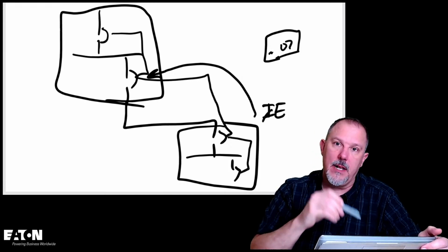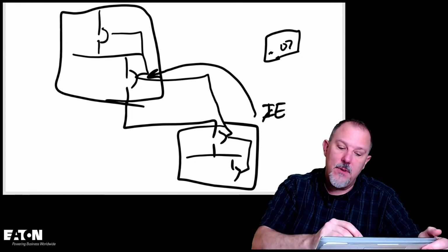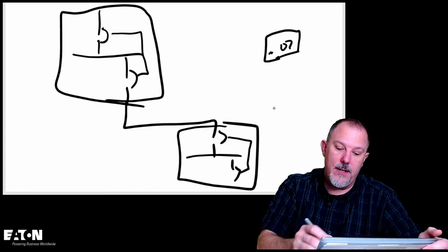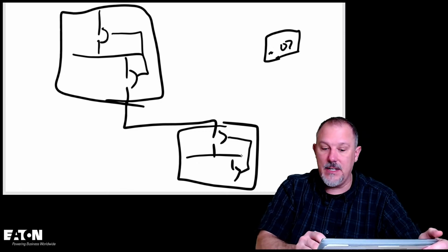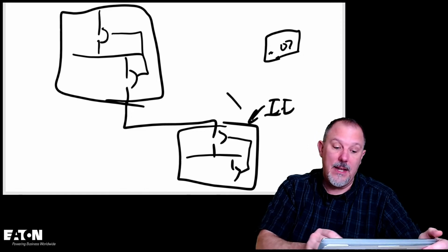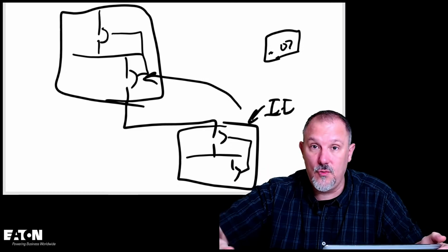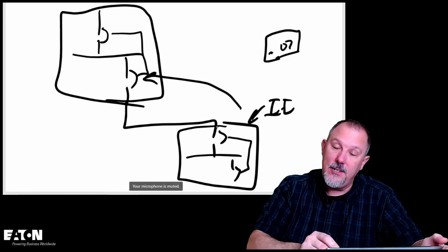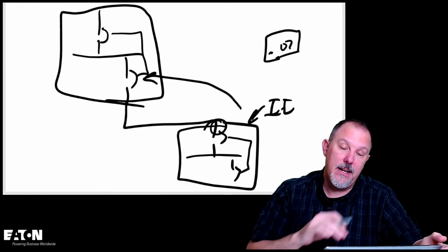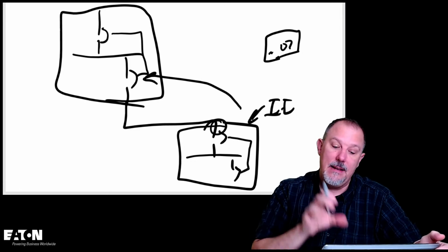So I can nest these, but if I'm not nesting it, if I zone selectively interlock these devices, the incident energy at this panel really is dependent upon the clearing time of that upstream overcurrent device, because I have to assume line side propagation on the line side lugs of those. And then it's based upon the upstream overcurrent device, even if I zone selectively interlock in that panel.